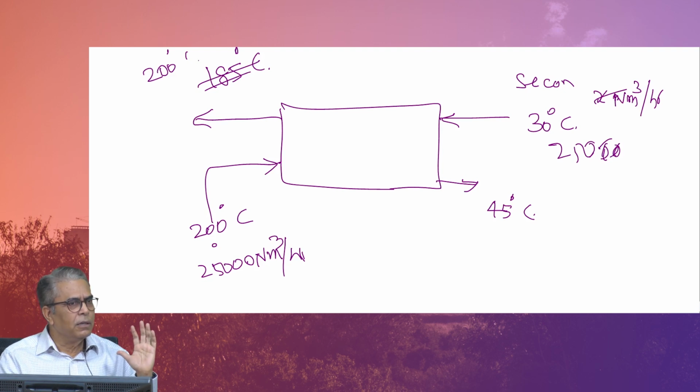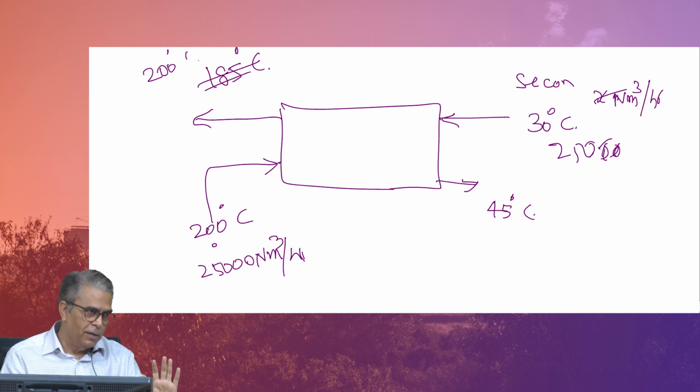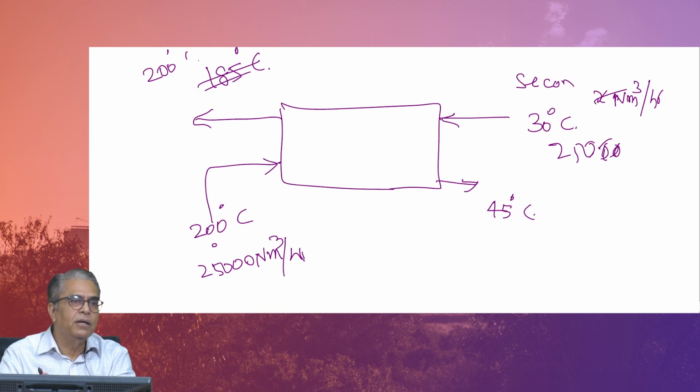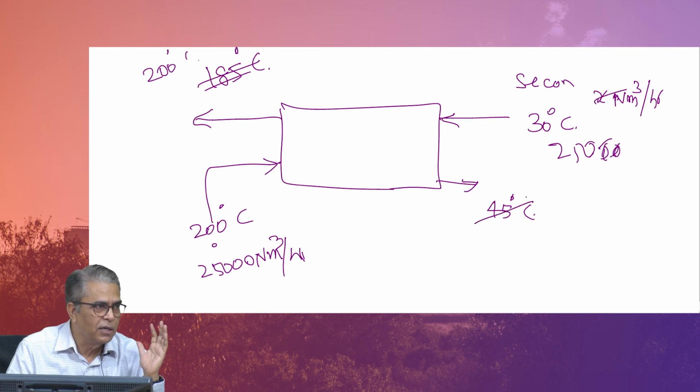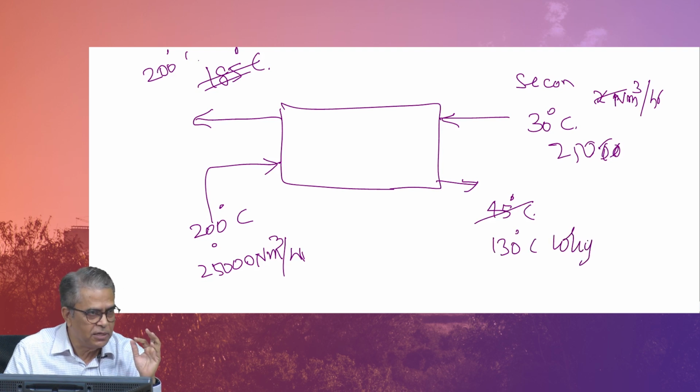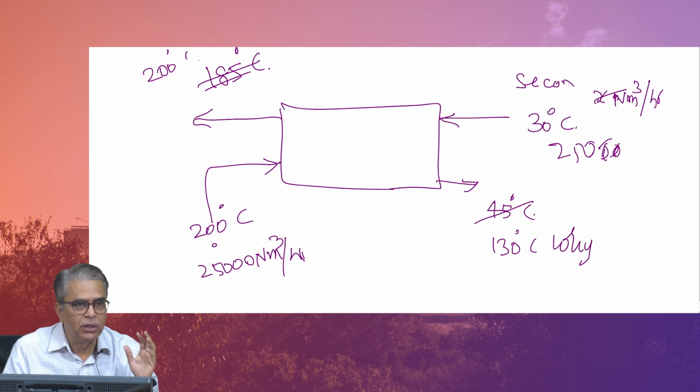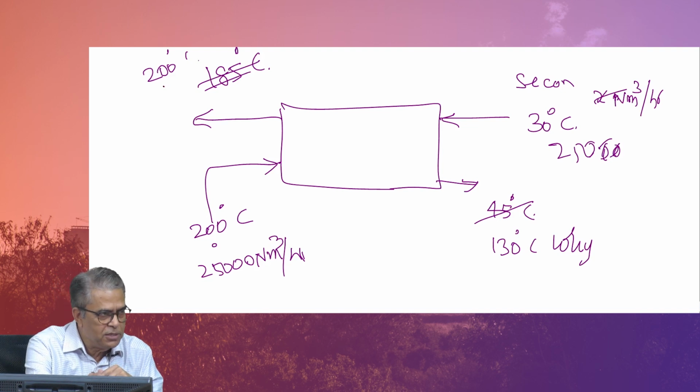You can say, wait a minute, you have not heard about corrosion resistant material in life, is it? I will go for graphite heat exchangers, these things are available today, what is the problem? You can, but that exchanger is definitely going to be a little more expensive. So, this is a bit of a trial and error business you have to go through. So, initially going by convention, normally people do not cool it down to less than 130, 140. Why? Because of the reasons I said. So, initially assume 130, then we will see why 130, why not 100 by superior material for 100. Then you will know this temperature will change.